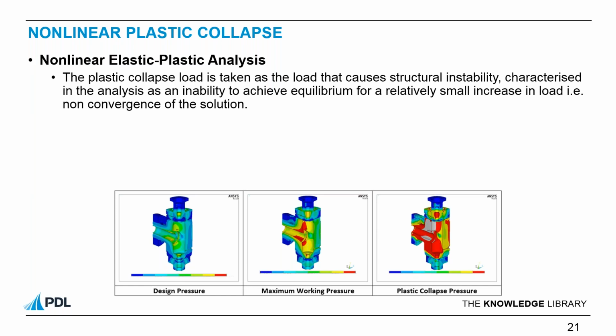By interrogating the results in the example on screen, the image on the right here, we can see regions in excess of the yield strength shown in red, and we can see huge regions like that. Regions in excess of the UTS are shown in grey, and we can see a significant enough proportion here such that we've observed a sectional failure.